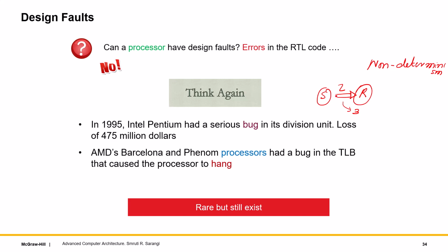So to fix that, we made all communication interfaces deterministic. Because anyway, inside logic, non-determinism doesn't happen to that extent because it's still synchronized at clock boundaries. But communication across clock boundaries or between 2 circuits within the clock boundary can introduce non-determinism, as many authors have pointed out.